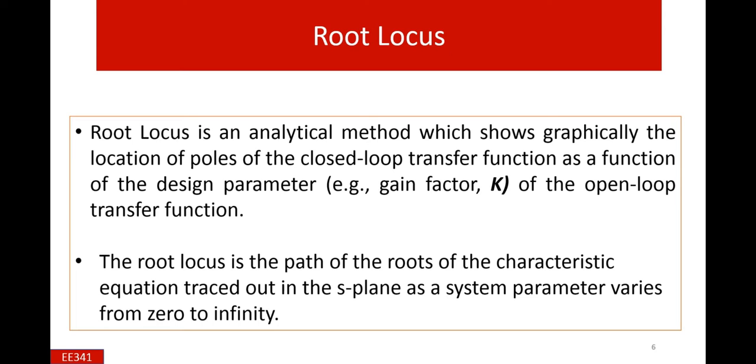If we put this characteristic equation equal to 0, then we can find the roots of the equation. There is a dynamic parameter, which is usually K, and if we change that K from 0 to infinity, actually not infinity, close to infinity, or from 0 to some maximum value, then the roots of that equation, which may be of any order, change accordingly. This is the root locus.